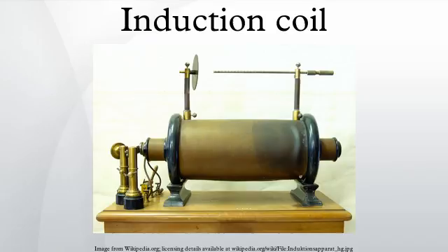The largest coils used either electrolytic or mercury turbine interrupters. The electrolytic or Wehnelt interrupter, invented by Arthur Wehnelt in 1899, consisted of a short platinum needle anode immersed in an electrolyte of dilute sulfuric acid, with the other side of the circuit connected to a lead plate cathode. When the primary current passed through it, hydrogen gas bubbles formed on the needle which repeatedly broke the circuit. This resulted in a primary current broken randomly at rates up to 2000 breaks per second. They were preferred for powering X-ray tubes. They produced a lot of heat, and due to the hydrogen could explode.